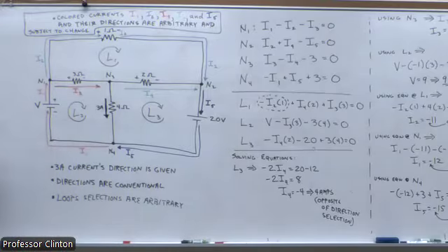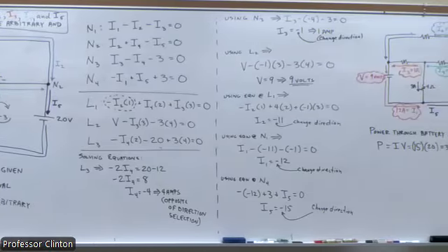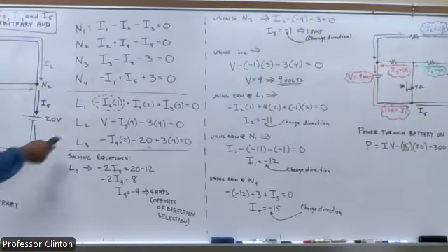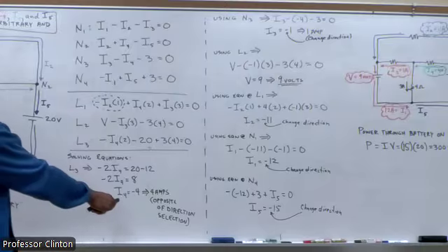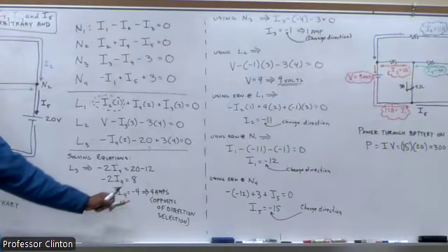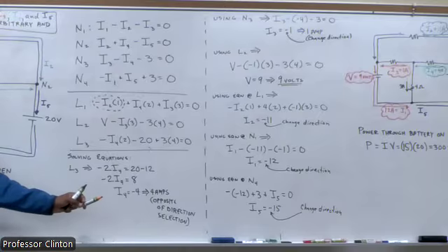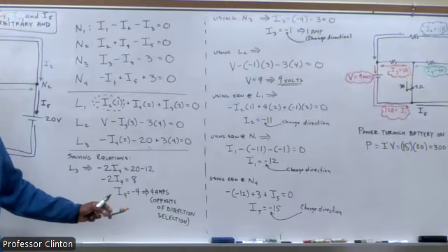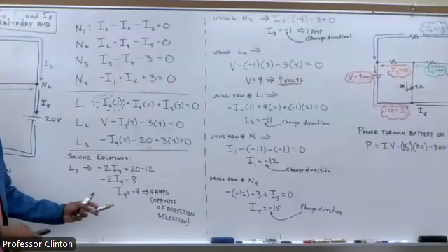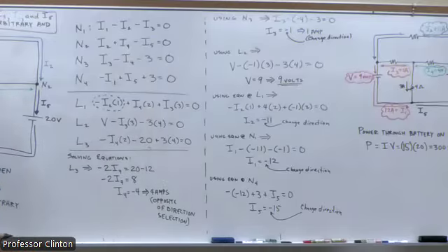And now it's sort of a puzzle piece. You have to figure out which equation leads you to what. So at this point, I'm going to start off with looking at L3 because that has the one unknown. So if I look at L3, I can easily solve that for I4. You'll notice that when you solve this for I4, the number is negative. Now, you're going to have to keep that in mind. And also, since we're dealing with the system, we don't want to change that numeric value just yet. So use that value when you start substituting into other equations.